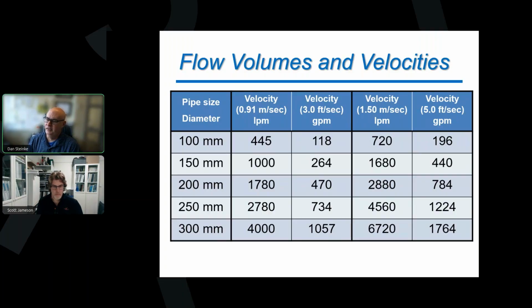Kirby is wondering, because I believe he asked a question before, just concerned about the PSI when flushing reducing to lower than 20 PSI. Yeah, so once again, when we go below that 20 psi, that's when we start entering that area where we're going to have back siphonage events happening. So that is why we try to make sure we stay above that limit, and not pull that water out of people's service lines of their homes and possibly contaminate our system.